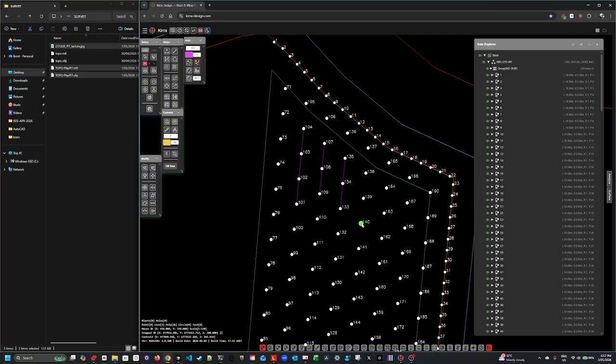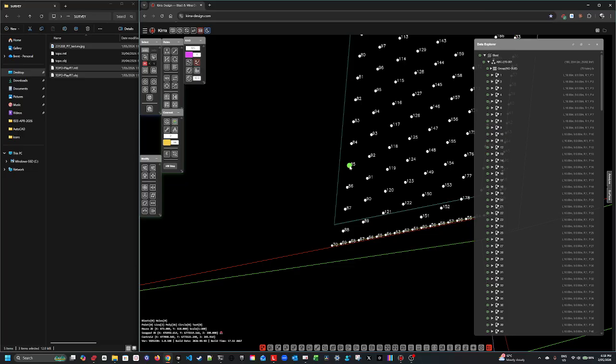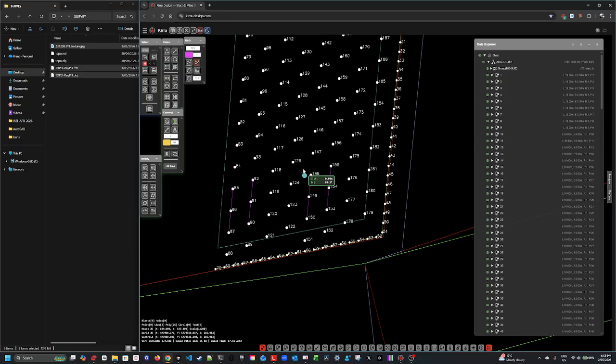Now, Kirra, the application, snaps automatically to these points. If you want to be close to it but you don't want to snap, you just zoom in, right? But working precisely is how you make people understand that drill and blast is not voodoo medicine or something like that. Drill and blast is actually a science in some format, and so doing this is key to this.